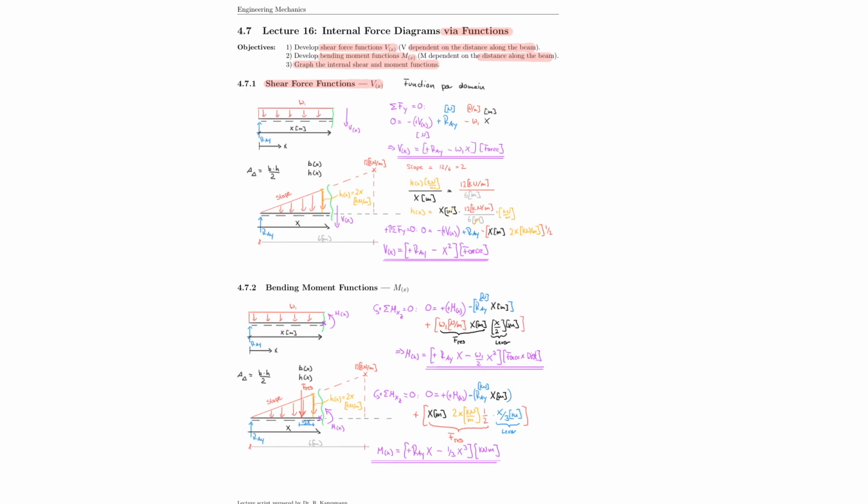And then, of course, you knew this before, that when you go from the shear force to the moment, you really bring up your function by another x. But I have now shown to you why that really is the case. So this is something that often causes headache to students in the classroom. So please go ahead and study these equations particularly. I hope I did a good job on explaining that, but please make sure that you really understand where the x square comes from and where the x cube comes from here in this case, right? And I say it again, x times x is the height and the base of the triangle, and then we have the lever arm, which also needs to be expressed in terms of x.